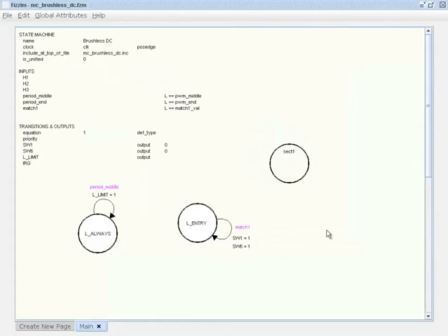If you remember the principle related to the Hall sensor feedback, we can determine when the motor has rotated into the next sector by observing the Hall sensor outputs. In particular, we will be able to determine when the motor has rotated or moved to the first sector when the Hall sensor signal H2 will be high.